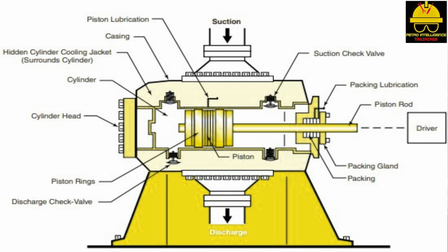Reciprocating piston compressors work by trapping and compressing specific amounts of gas between a piston and the cylinder wall. The back-and-forth motion incorporated by a reciprocating compressor pulls gas in on the suction or intake stroke and discharges it on the other. Spring-loaded suction and discharge valves work automatically as the piston moves up and down in the cylinder chamber. The basic parts of a reciprocating piston compressor are shown in picture.